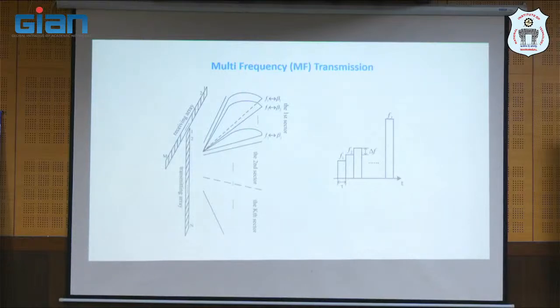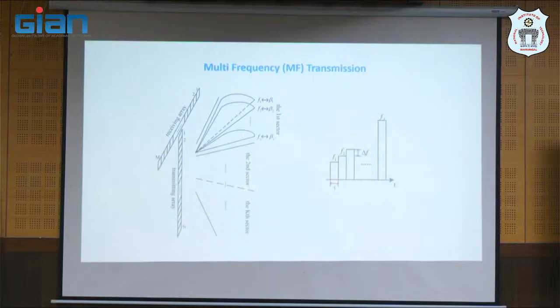To achieve real-time processing, there are different kinds of techniques. One particular technique proposed by a team is to divide the transmitting sector into different sectors, and for each direction, transmit one single frequency. Say, for beta 1 direction transmit F1, next direction F2, and each beam width will be tau. Like that we cover it. So we don't need to wait for all the beams to come back. We can sequentially drive as per this timing and cover this area very quickly. We don't need to wait.